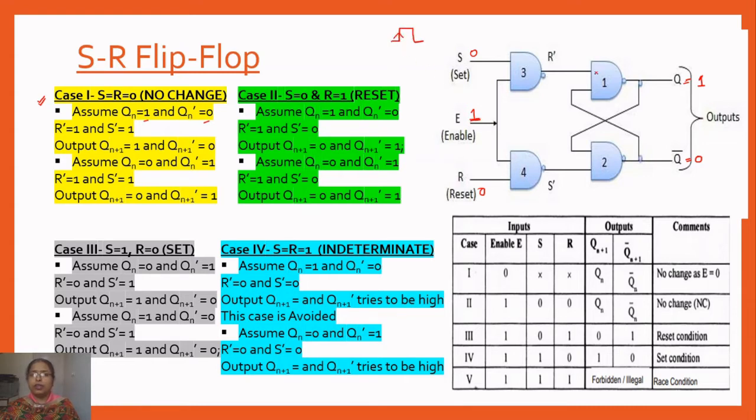and we are writing it here as high, right? So this is a NAND gate, and as we know, the output of the NAND gate is high when any of the input is low. So as you can see, one low is there, 0, 1, 0. So this will be 1. Similarly, the output of the 4th NAND gate will be high.